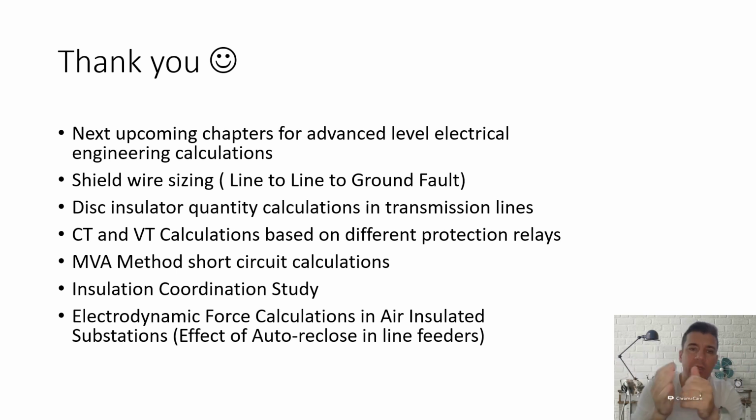Classification, class 1, 2, 3, depending on the transmission line length, and where to put that surge arrester to protect in front of that transformer or in front of that substation. Then I will try to explain when it is required to put them on both sides or only one side of these underground cables to protect them.